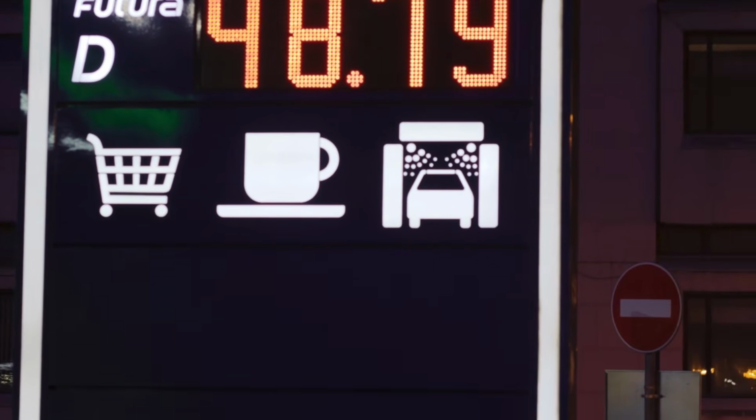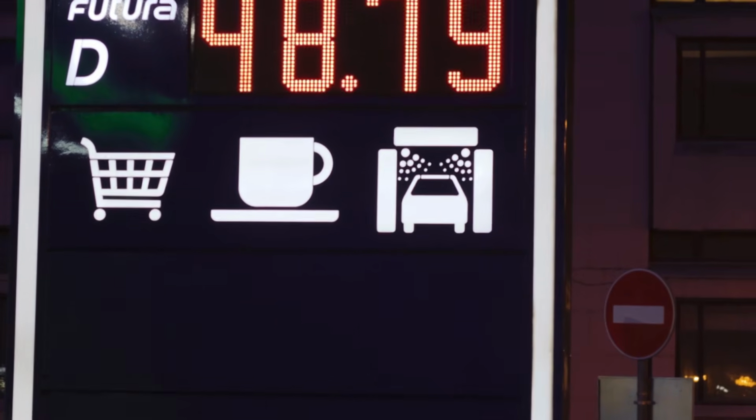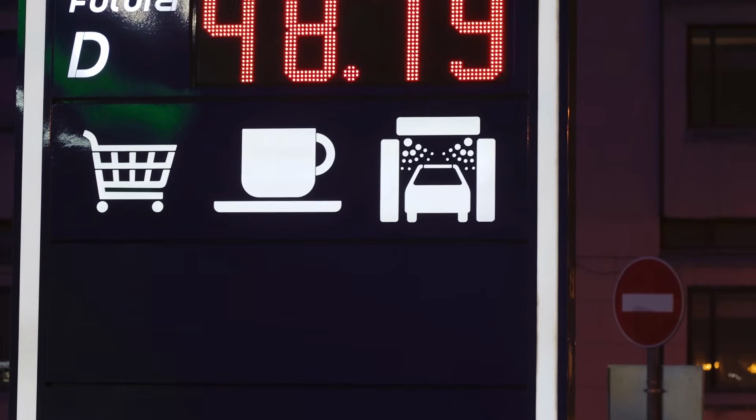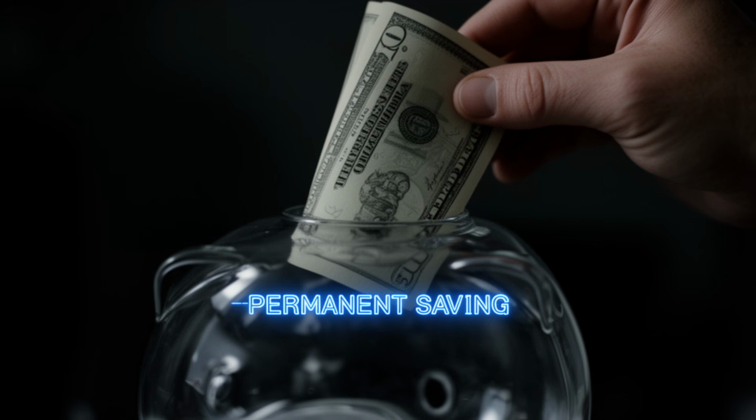In 2026 fuel cost terms, at an average US price of $3.70 per gallon of regular unleaded, a driver covering 13,500 miles per year in a vehicle that improves from 28 mpg to 32 mpg saves approximately $68 per year. That is not a dramatic number in isolation. But it is a permanent saving, achieved for a one-time investment of under $10 in materials and 30 minutes of time. And it compounds. Better air-fuel ratio means more complete combustion, which means less carbon buildup on intake valves and combustion chambers, which extends the service life of components downstream.